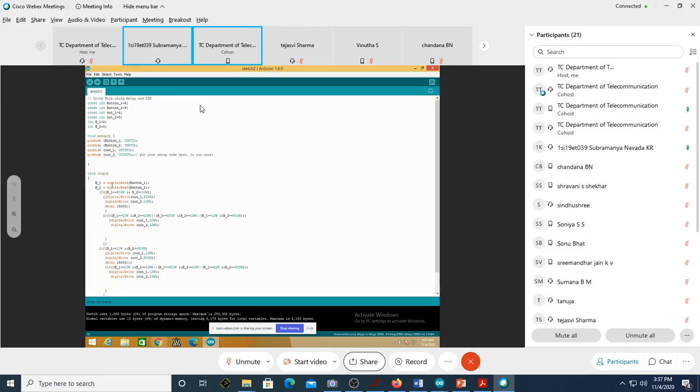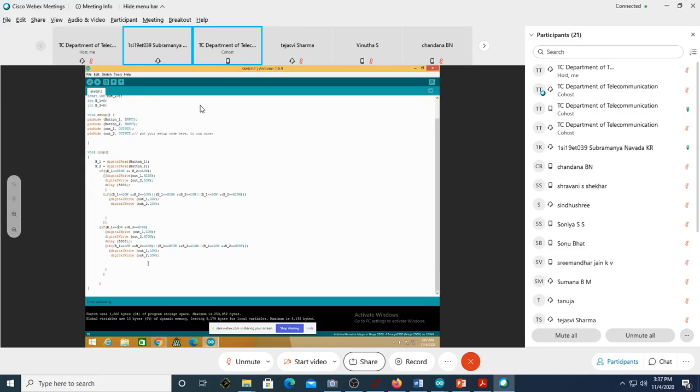The digital read values: if B1 is low and B2 is high, just see what is the digital write of output 1 and output 2. It's the inverse of it. Are they exactly opposite to the first case? Now what will happen? It runs in the opposite direction. The buffer which was sourcing now starts sinking, and the one which was sinking now starts sourcing.